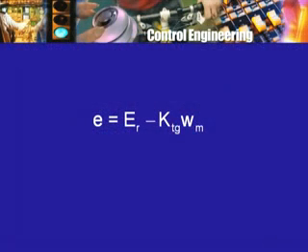So what are these equations? Well, what are the signals that we have introduced, the additional signals that we have introduced? We had introduced the error signal E. This error signal E was the difference of the reference signal ER minus the tacho generator voltage, and we could write it directly now as K tacho generator, that is some coefficient multiplying the motor speed.